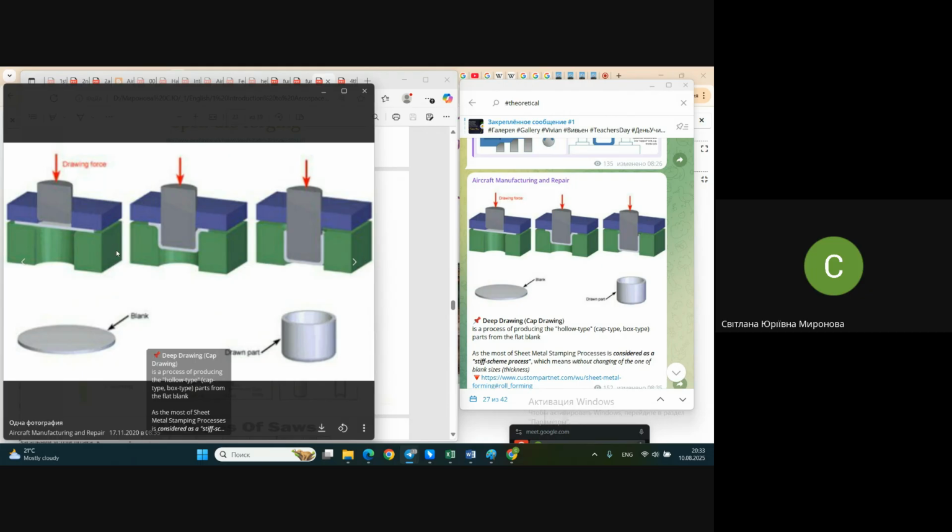Maybe it's difficult to understand the first time, but I hope you remember what I explained about the inner structure of metal, and that deformation results in a change of structure. Moreover, the structure may even be spoiled in the process of deformation. If deformations are higher than the so-called ultimate deformation, the part is broken during the technological process. It just cracks, and that's it.